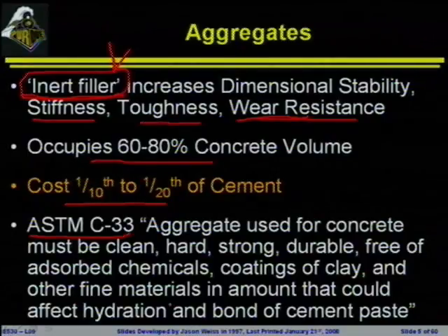Many times if we start looking at trying to recycle old concrete and using it as aggregate, it may have absorbed chemicals in it. We may run into aggregate seams that have clay in it that we need to figure out how to use. We may have aggregate that's not that hard or that strong, and we need to figure out a way to use it. So these are things that we should be keeping aware. This is sort of an ideal definition. We may end up having to use aggregates that are a little bit different and trying to design ways to do that.